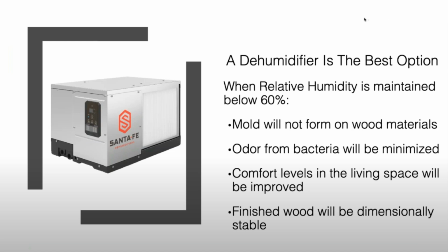The dehumidifier is the best option because you can set it to control RH and keep it below 60%. Microbial growth or mold will not form on wood materials. Odor from bacteria will be minimized. Again, if there's a musty odor in the living space of a structure, there is some sort of bacterial microbial growth. Comfort levels in the living space will actually be improved.